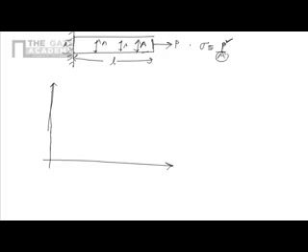Now, if we take the stress along y-axis and the strain along x-axis, and we do this experiment, which is that the specimen is taken to a machine which is known as Universal Testing Machine, UTM, and there it is pulled with a force which is slowly increasing.